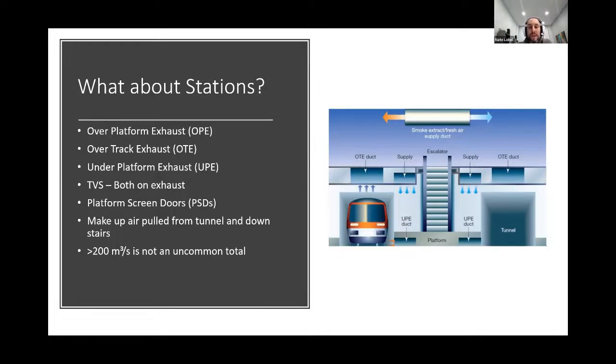And to me, what's quite interesting here is, earlier I was saying how in a building we send smoke up and people down. Obviously, in an underground station, we're sending people up. And when you're doing modeling, one of the things you might be looking at is, can you get about 1 meter a second across the stair that goes down onto the platform? That's effectively you're trying to create enough flow of makeup air from upstairs and from outside that you can pin the smoke to the platform, so that once people are upstairs, they're safe. So it's sort of the reverse of buildings. You're keeping the smoke down and the people up.